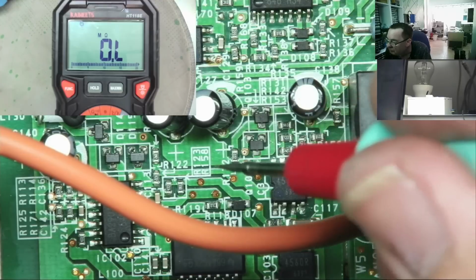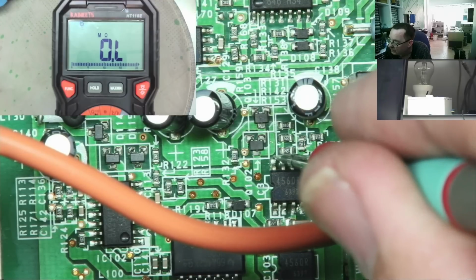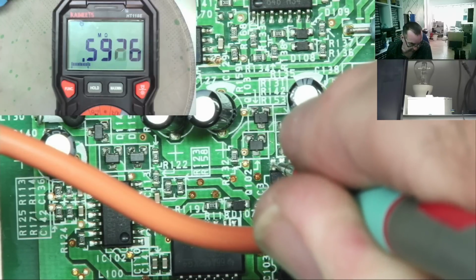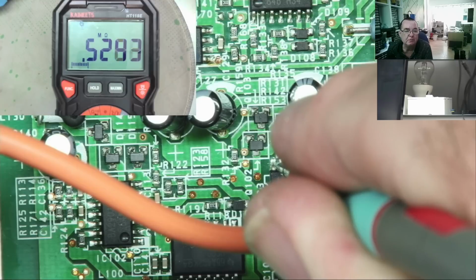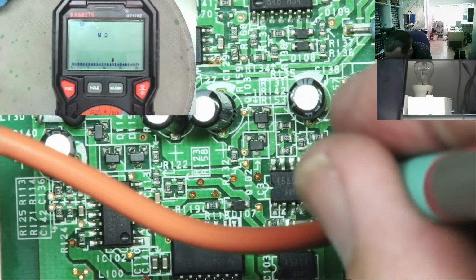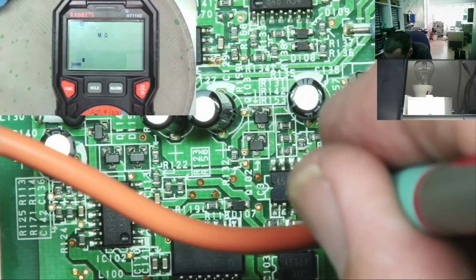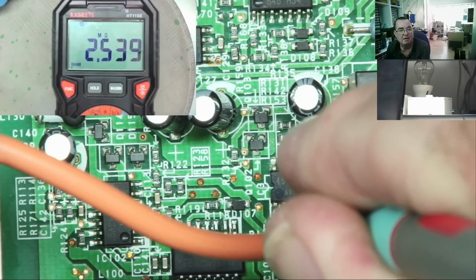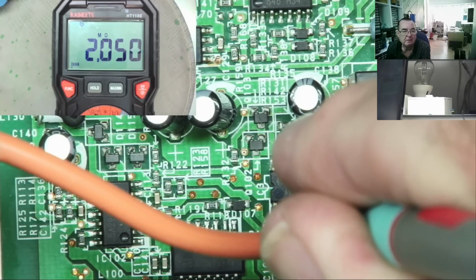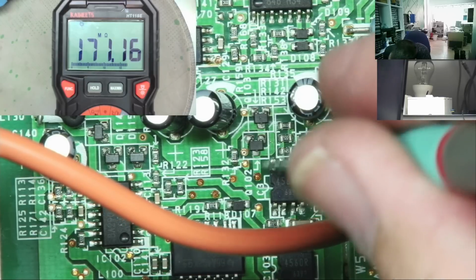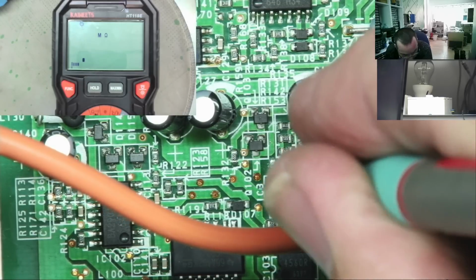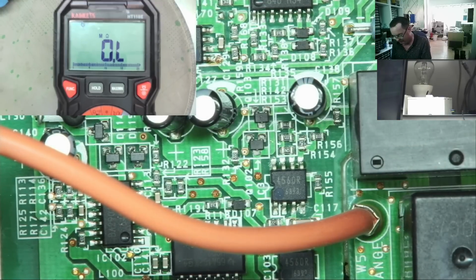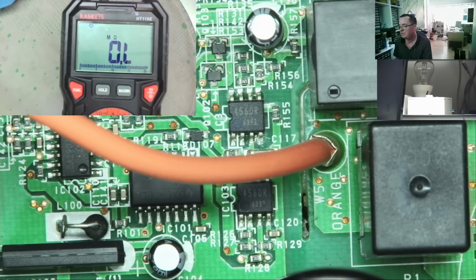Resistance range. It may not read correctly if there's a bit of voltage here. Let's see. So that reads about 500k or something like that, yeah. This one. It reads high, so there's no short there or low resistance. I was just wondering if something was drawing a lot of power and pulling that rail down. I mean, it just doesn't seem right, but bear in mind, I've never worked on one of these before. I just don't quite get it.